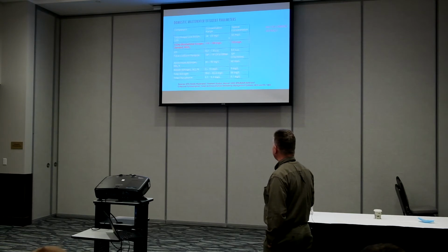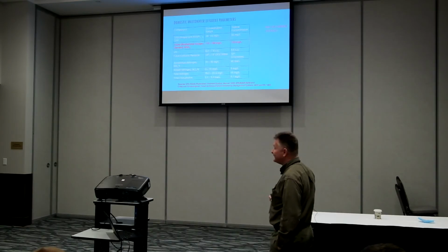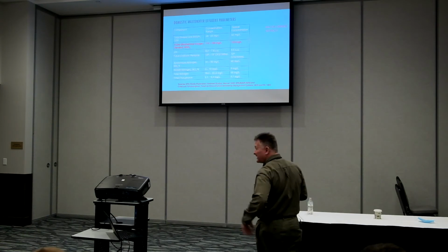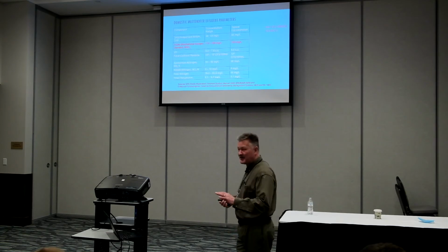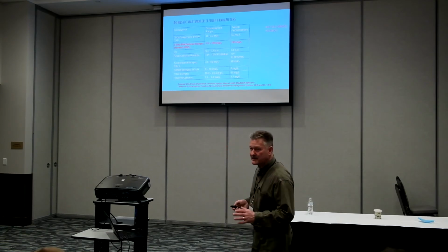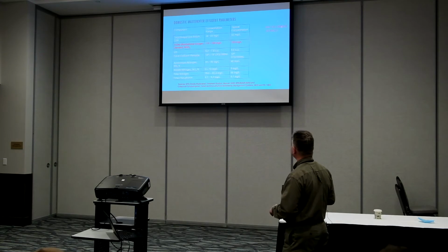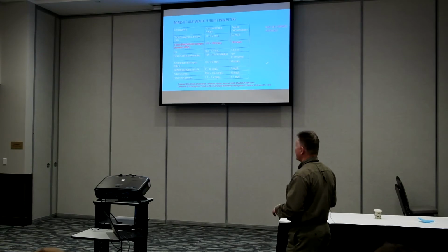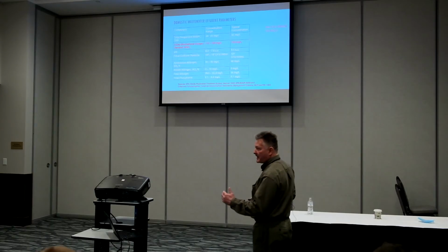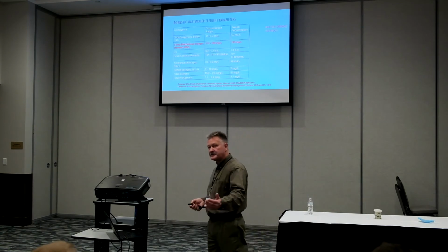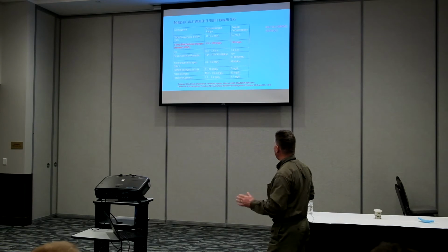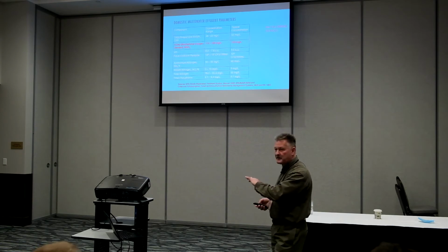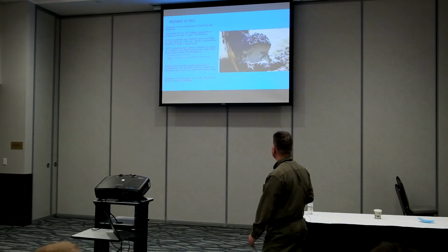So for a typical domestic residential system, you're going to have a range right here, 120 to 189, basically anything under 200. Typically, you're going to see about 120 to 140 if everything's working properly. And one thing this chart doesn't have is fat, oil, and greases. Typically coming out of a domestic septic tank, that is under 20. So pay attention to those numbers because we'll use those as reference for the rest of the presentation.